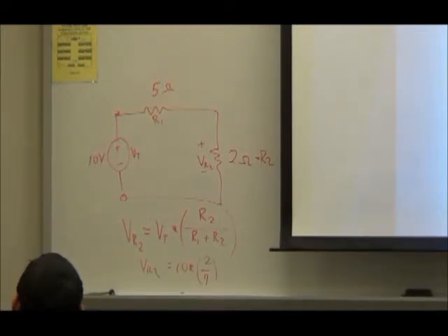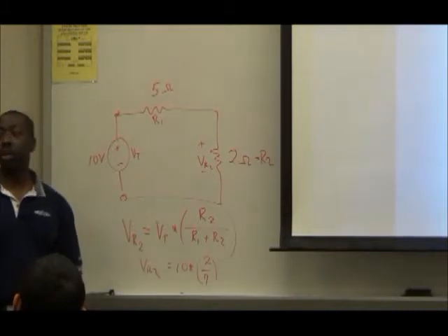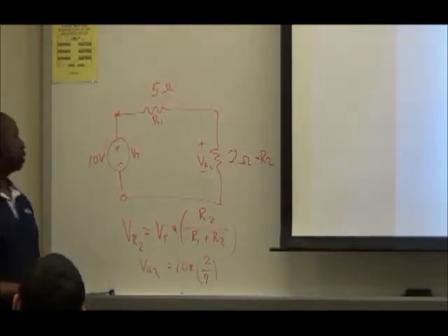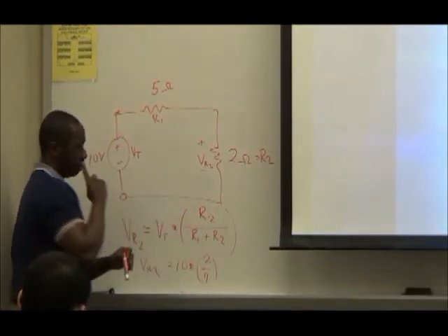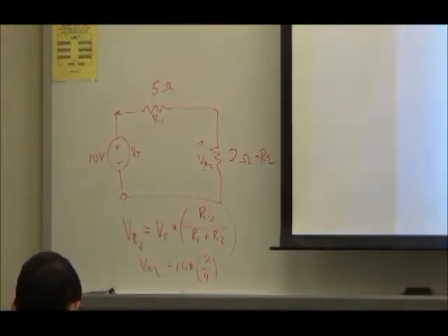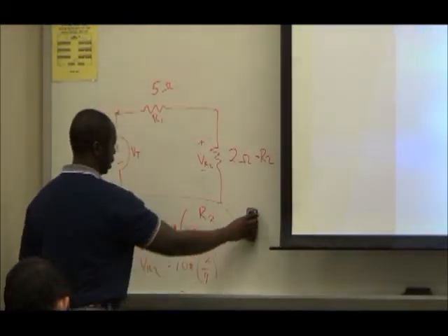So if it's 3 of them, and they all have the exact same number, who cares what the number is? You just take that voltage source and divide it by 3, and that'll give you the value. Let me go ahead and erase this, but before I erase, I just want to make a point so that you can quickly see this on the exam if it comes up.